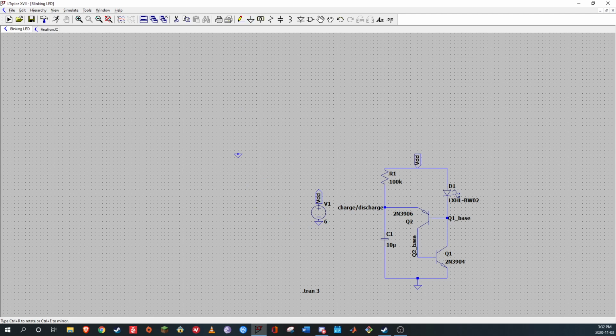Cool. So now, no matter where this voltage source is on your schematic, it's always going to be feeding this net that it's associated with. Which for this schematic isn't super important, but it is nice later because you'll have stuff with like 3 or 4 voltage sources and like 2 constant current sources, and it's nice to just have them all side by side so you can really quickly click on whatever you need to see when you're simulating the circuit. Now I've also gone and made nets.